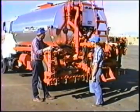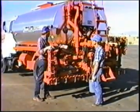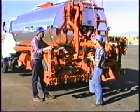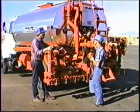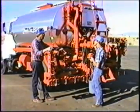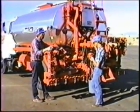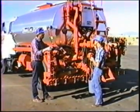Now, if we didn't have the computer, we still make the setup just as we started out here. With the cardboard computer, we pick a travel speed, we set the desired spread rate on that, read the bar width, and then adjust the asphalt pump to that gallons per minute that we read on the cardboard calculator, when we drive the truck at that particular speed.